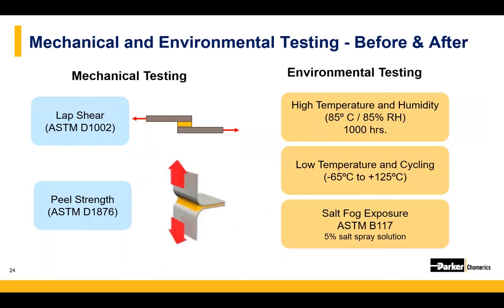Thanks. So mechanical testing actually uses the adhesives and sealants attached to a couple different aluminum test panels that are pulled apart until the breaking point, and that's per the specific test procedure. The force that's recorded at that break is measured and then recorded as the lap shear force.